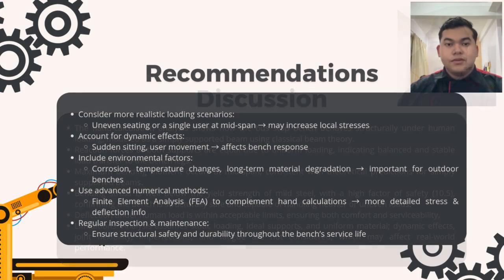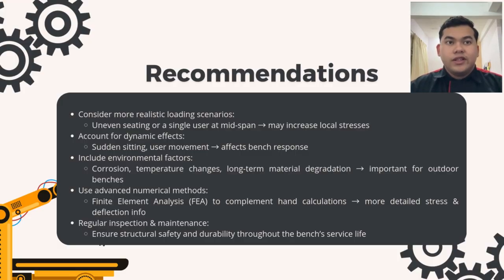Thank you. Now, let's move to the recommendation part. Number 1, consider more realistic loading scenarios. In our analysis, we assume the human load is evenly distributed across the bench. In reality, people might sit unevenly, or a single person might sit right in the middle. This can create high local stresses at certain points,